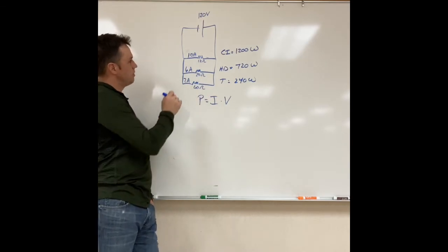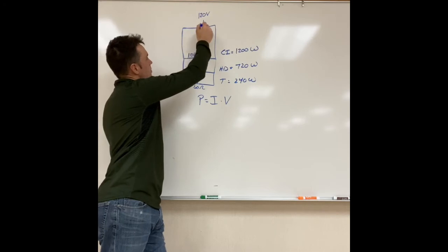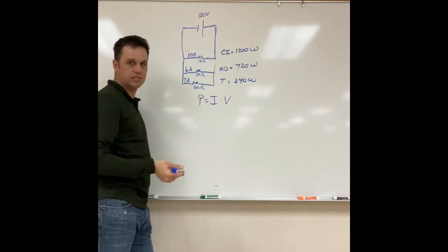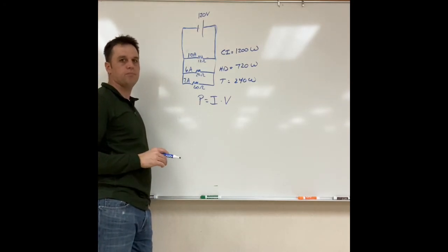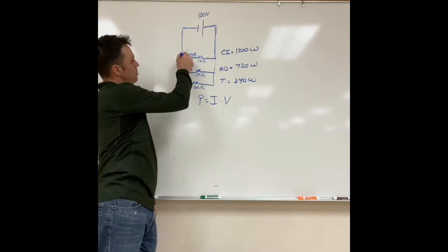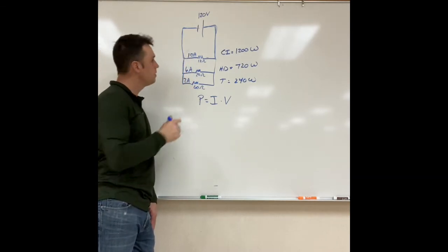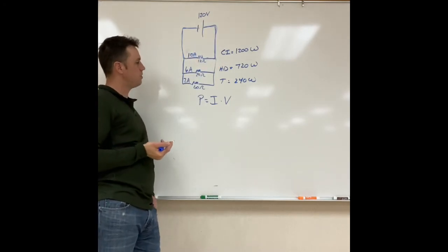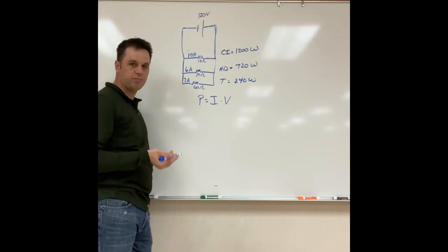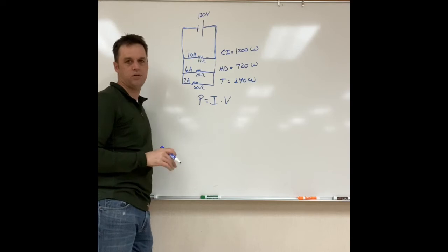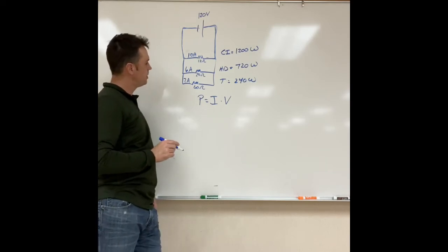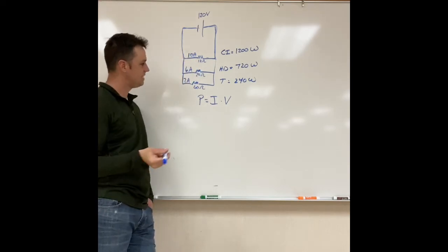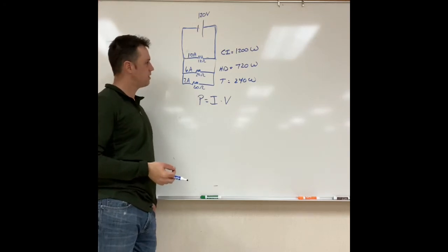An interesting thing is when you get to the main part of the circuit, right here, like in my house, these would be called the home runs. They would be going back to the garage, where all the outlets have dumped together. Like these would be each individual outlets that I might have something plugged into. These runs will be going back to the breaker. And in my house, if you get over 15 amps in the bedroom, you're gonna trip the breaker. And then you have to go out and reset it. But let's say you had a 20 amp circuit breaker. Would we trip it? 10 amps and 6 amps and 2 amps. When they all dump together, you'd have 18 amps, so you'd still be okay. So this would not trip the breaker.